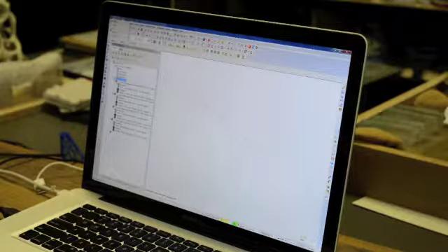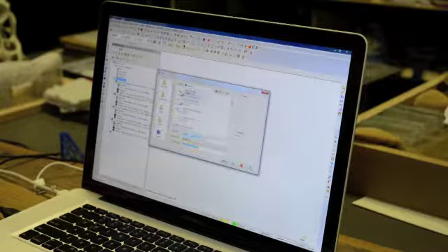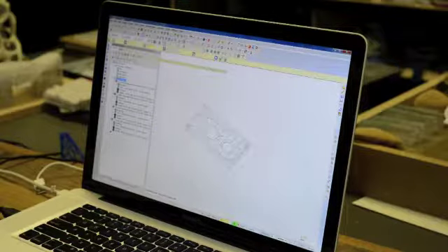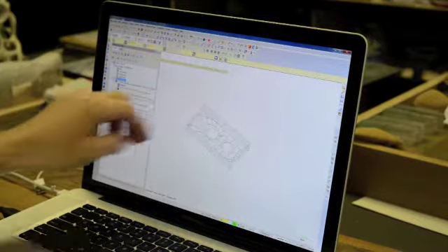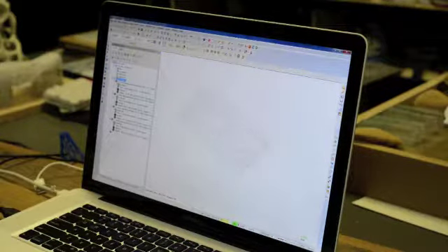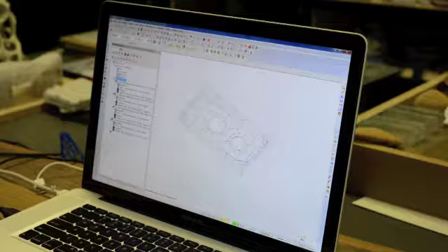So here's where we do our file merge, and we want that one, the bottom. Oh, 3DM mill test May 2014 bottom. Bring that in, and all this stuff is kind of highlighted, just giving you some options when you brought it in. Just hit escape, and now over here you just have to go through the same process of selecting drive surfaces, containment, yada yada. But that's a real time saver.